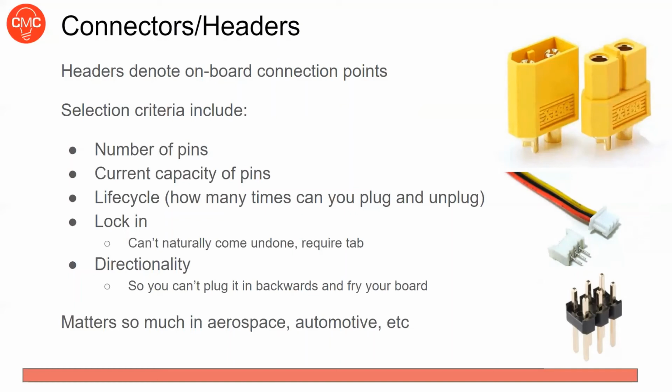Now, some are also directional or keyed, which means you can only plug it in one direction. This is really huge for power cables because if you plug in a battery backwards, you could damage the board and the battery and possibly cause a fire. I've also done that before.